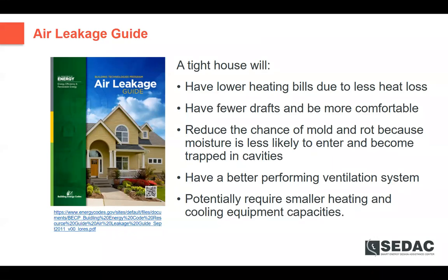So, a tight house will have lower heating bills, which, as energy becomes more expensive, is a big deal. It'll be more comfortable, with fewer drafts. When we have air leaks, there's a potential for warmer, humid air to leak out when it's exfiltrating and then condense inside cavities in the building and cause problems.